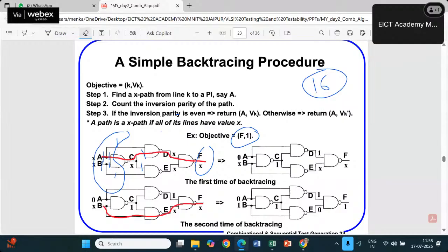You can take this as an exercise, as an assignment, and do the fault equivalence and dominance based collapsing, and you can figure out that you will have 16 or fewer faults in this particular case. That verifies the checkpoint theorem discussed earlier.